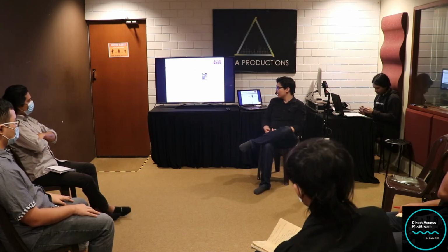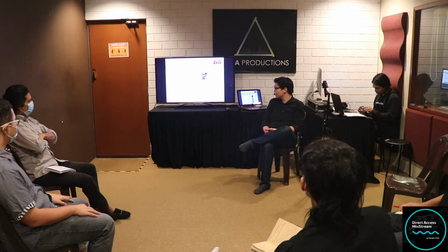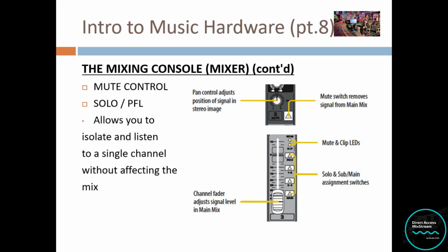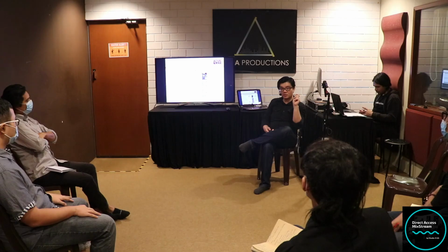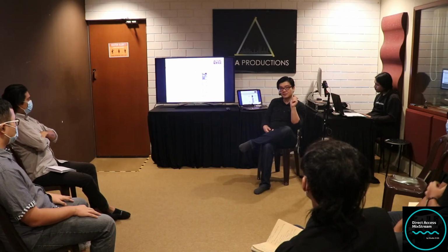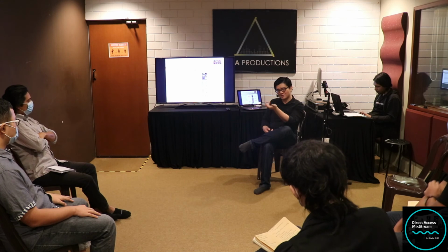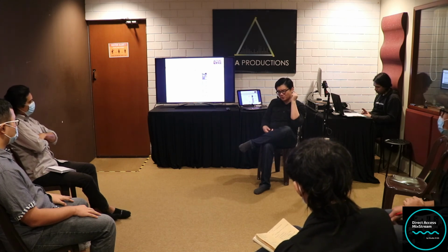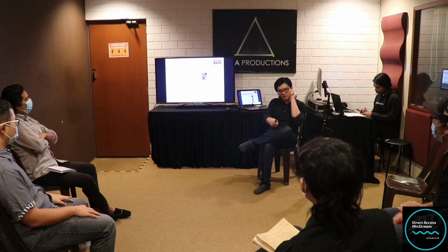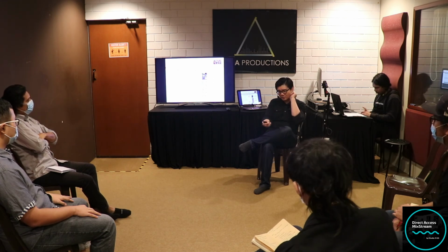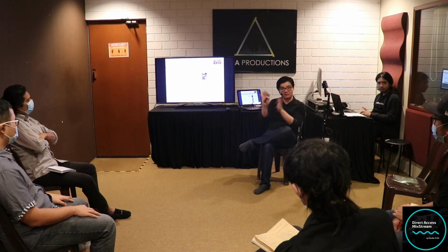Now, all right, a lot of technical stuff. The solo PFL allows you to isolate and listen to a single channel, or sometimes a group of channels, without affecting the mix. That's basically what a PFL button does. So it doesn't affect the main mix. You just solo slash PFL so that you can listen to it. You can adjust the tone, the EQ, whatever settings of the channel you're listening to, and it doesn't affect the mix.